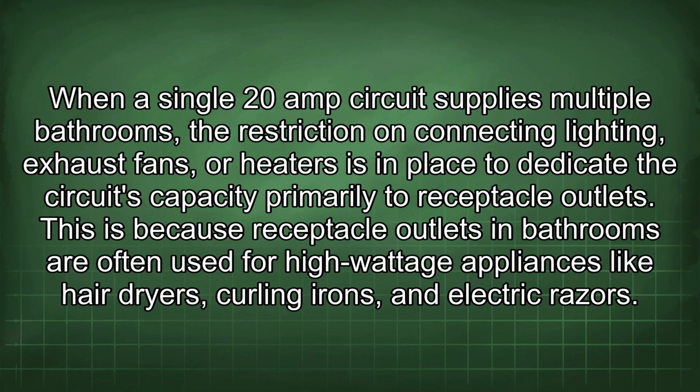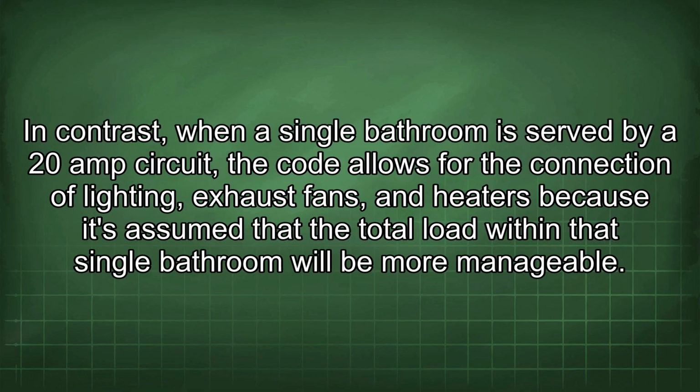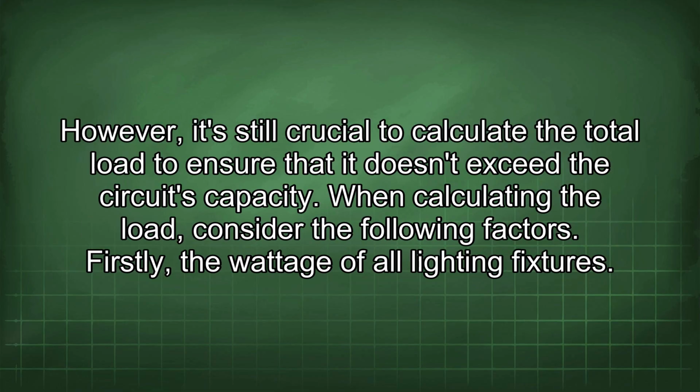This is because receptacle outlets in bathrooms are often used for high wattage appliances like hair dryers, curling irons, and electric razors. These appliances can draw a significant amount of current, and if other loads are connected to the same circuit, it could easily become overloaded. In contrast, when a single bathroom is served by a 20 amp circuit, the code allows for the connection of lighting, exhaust fans, and heaters because it's assumed that the total load within that single bathroom will be more manageable. However, it's still crucial to calculate the total load to ensure that it doesn't exceed the circuit's capacity.